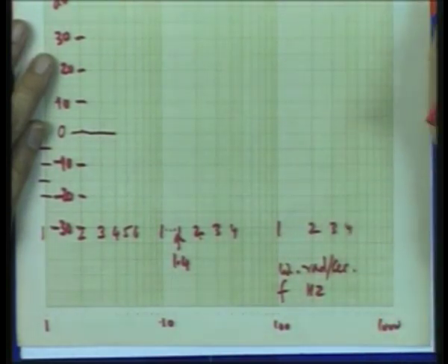So, with this semi-logarithmic paper, then using Bode's approximation, one can get a fairly good idea of how the gain is going to vary with frequency over the range of interest. And the range of interest is usually what? The smallest corner frequency, say about a decade below that or 1/10 of that, the largest corner frequency a decade above that, that is 10 times that frequency.